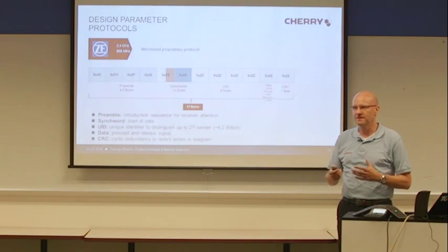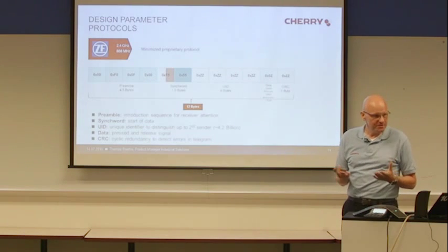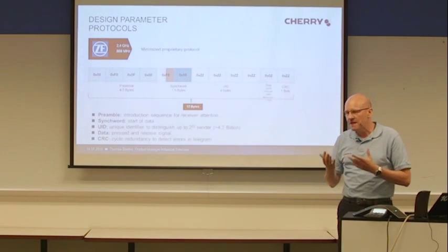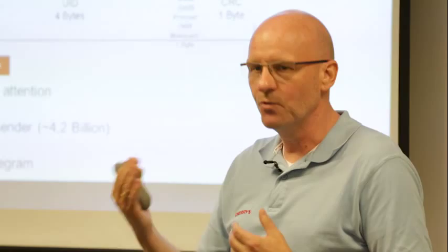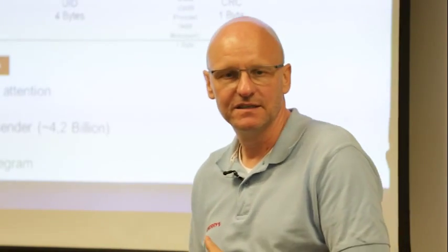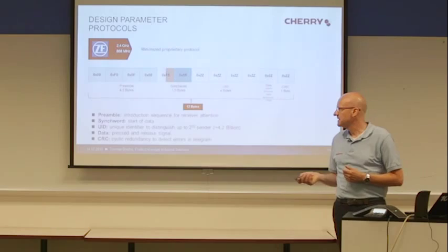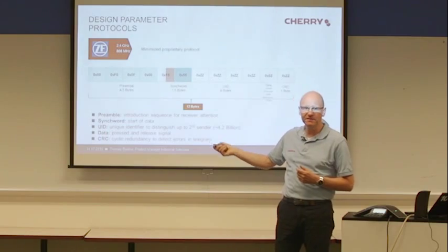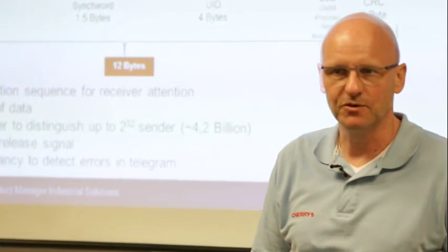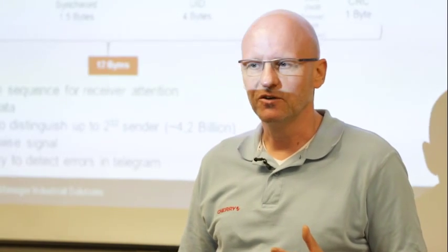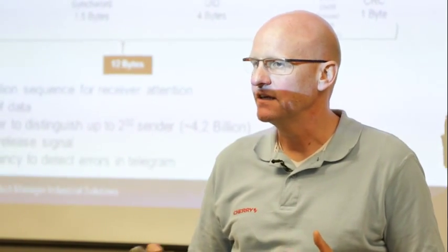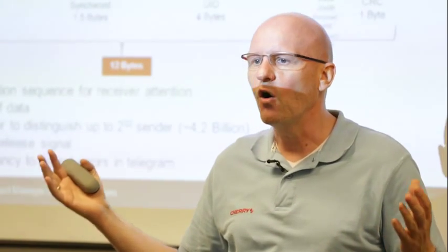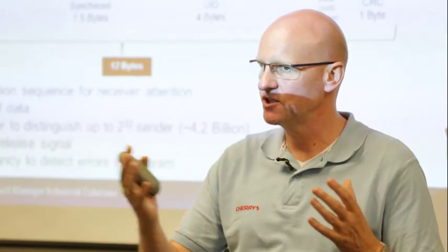And this is also a physical regulation of RF. You need a special design of your RF protocol so that it works over the RF channel, so that receiver and sender understand each other. So, for example, at first you need a so-called preamble. The preamble is the introduction sequence of an RF protocol. When the sender sends out an RF signal, the receiver catches all the signals on this RF channel.